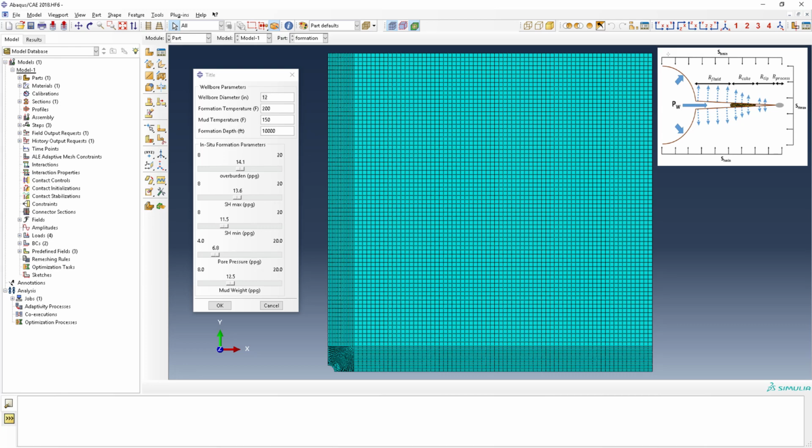Now that we have some context, let's look at an example of these solutions in practice. Here's an example of a templatized Abaqus model that is used to predict the behavior of a 6-inch horizontal crack present in a wellbore. The wellbore is idealized as a plane strain model looking down the well axis.